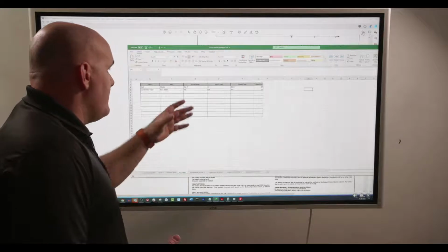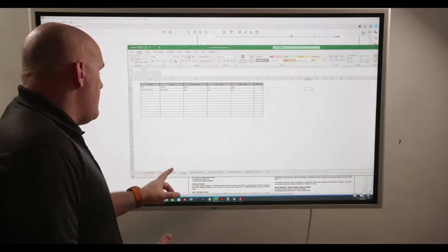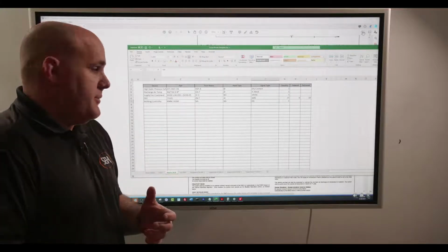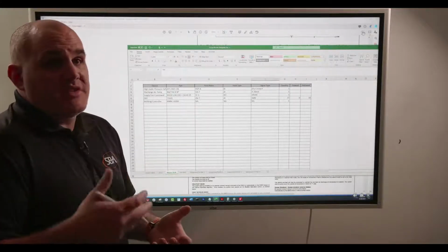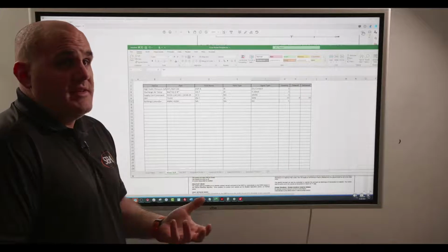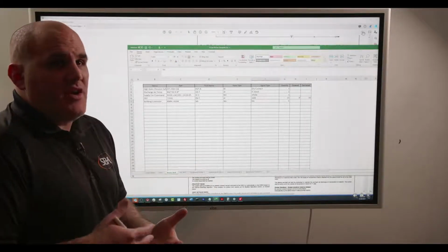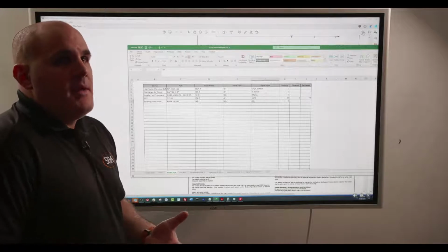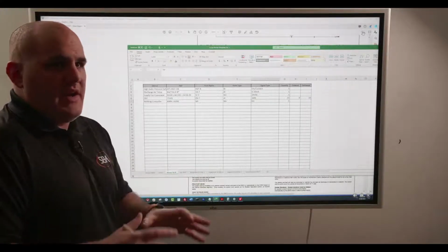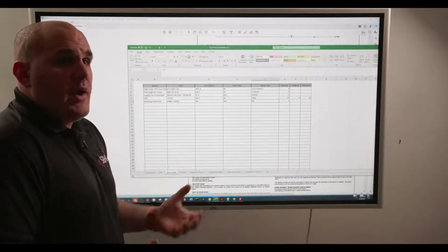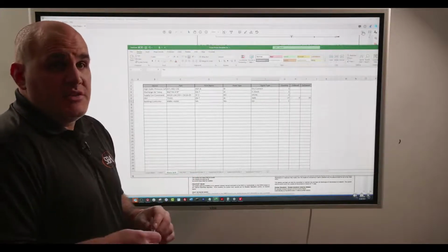And then once you've done that, you put it all into a master bill of materials, and you quote that master bill of materials. Then you assign labor costs and you assign your subcontractor costs. That's my approach to performing takeoffs, with a little bit of estimating built into that. I should have probably divided those out, but they're kind of interrelated. So I'm going to go over and see what questions you have.